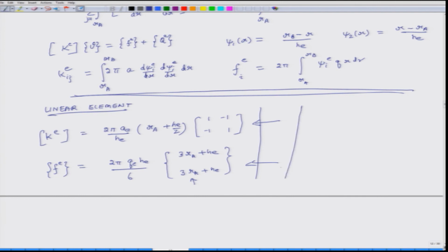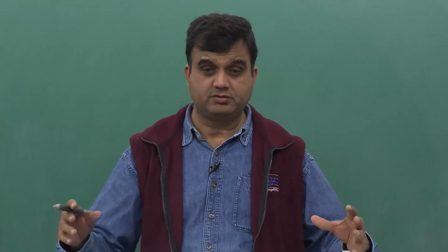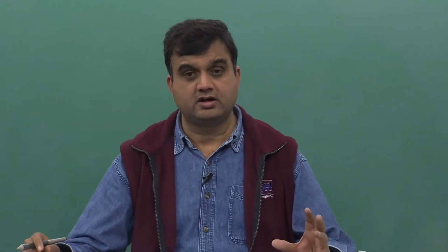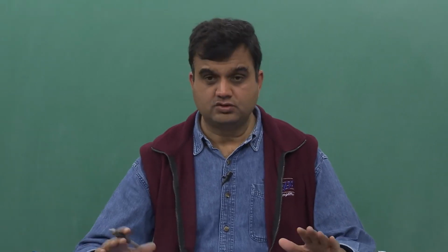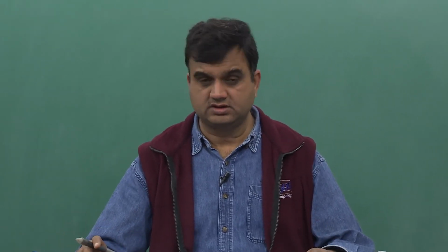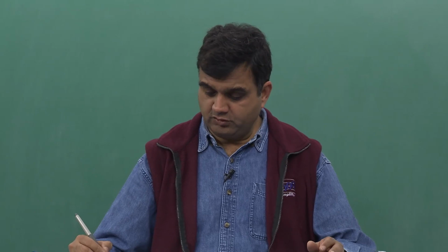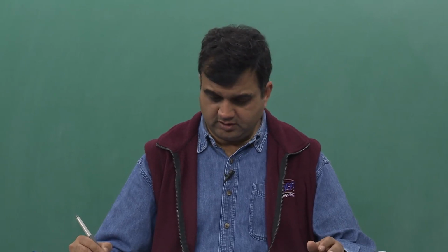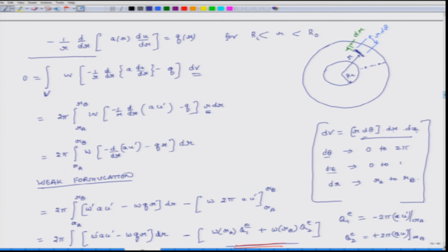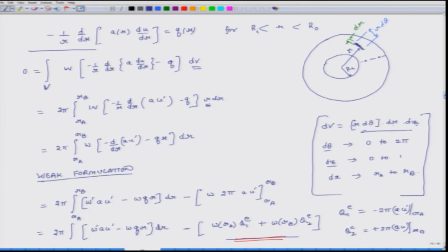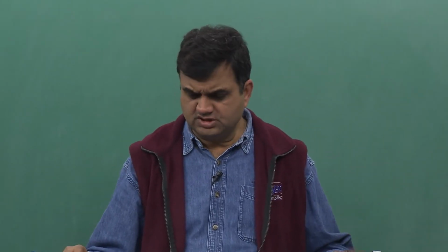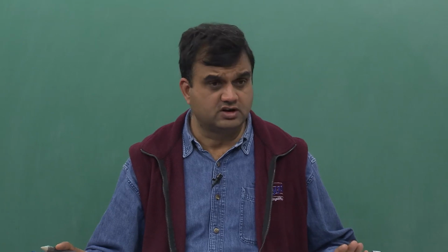So, this is what I wanted to discuss in context of radially symmetric problems for cylindrical coordinate systems, and you can use this formulation to address some of your needs. This is also a one dimensional problem, but its formulation requires a little different approach, because here you just do not integrate it with respect to dx, dy, dz. Rather, the definition of dv is r d theta times dr times dz. So, in the formulation things become slightly different. So, this is what I wanted to discuss today in context of radially symmetric problems.